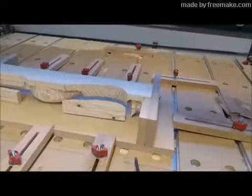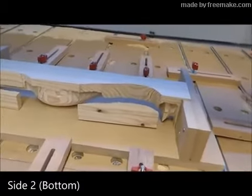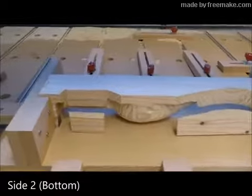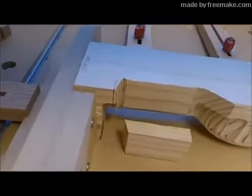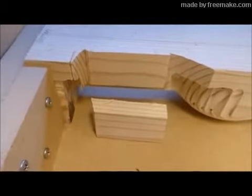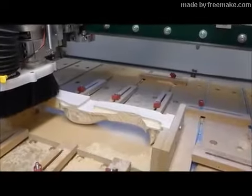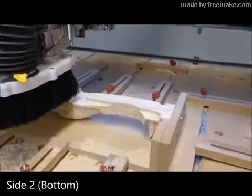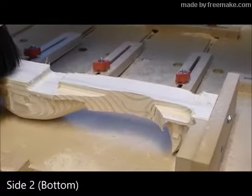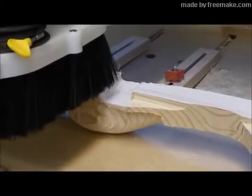Here the stock has been remounted in the jig, this time with the bottom side now facing in the upward direction. To lessen wear and tear on the ball mill, I used the bandsaw to cut out the pieces which are laying next to the stock. This is the roughing pass on the bottom side. Note that the CNC's dust collection shoe is in position now.